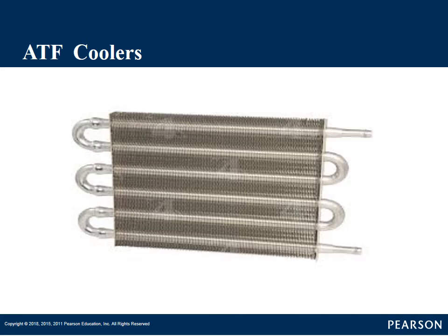As you can see, you've got tubes running back and forth in a crisscross pattern, almost like a snake, running through thin metal fins. The idea is this fluid runs through those tubes, air flows across those fins, the heat from that fluid is pulled into those fins, and then the air removes that heat from the fins.